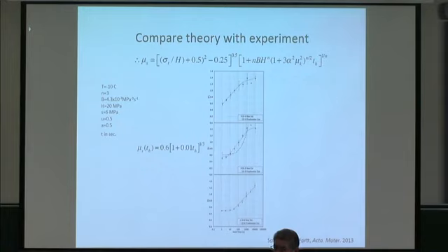You might wonder, well, surely the B value should be different for sea ice than it is for freshwater ice, because as everyone knows, sea ice creeps about 10 times more rapidly than freshwater ice, typically. But I would remind you that the asperities themselves are only about 30 microns, at least from this analysis. And if you remember one of the images I showed earlier, the brine pockets are separated by a distance greater than that. And so it's likely, we think, that even in sea ice, the asperity is just a piece of freshwater ice sticking out from the surface. And so the B parameter for freshwater ice is probably appropriate for both cases.